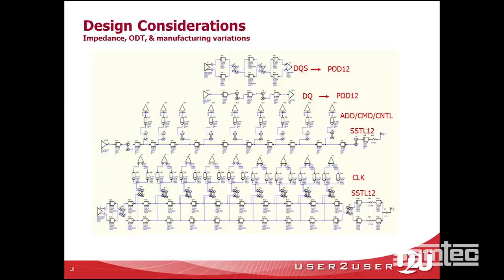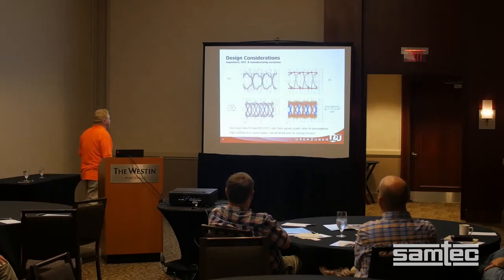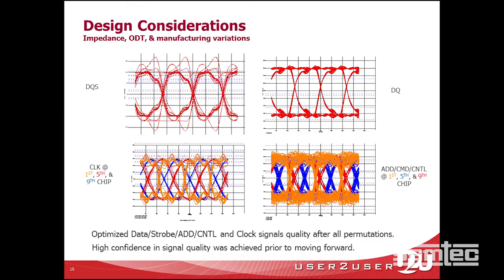And here's your clock, which is a differential pair. So you can do this by hand, which I've done, or you can extract this from a routed board. And from that, you can do your simulations, moving these around, making variations, so that you can do your corners.